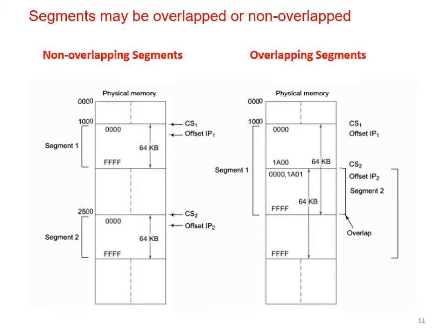You will reach the beginning of that particular segment by using your code segment register value, and from there you have to move some more. For example, suppose your code segment register was street number 7, and from the beginning of that street you need to go further to 79. How far you need to move is given by the offset register.